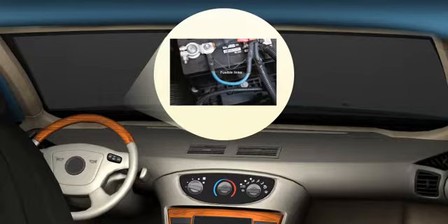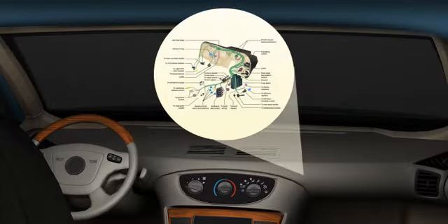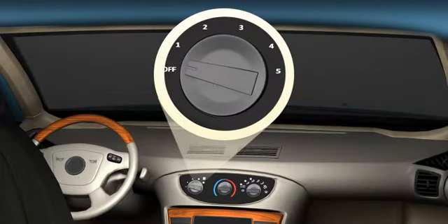The output of the battery should maintain a constant 12.6 volts. The conductors carry the electricity to the various parts of the circuit. The conductors are sized based on the amperage they will be required to carry for the circuit they are energizing. Sizing of the conductors is important so as not to burn the wires if undersized. The selector switch is a multi-position switch that allows the occupant to select the speed of the blower. The selector switch usually has 4 to 5 speeds depending on the vehicle manufacturer.